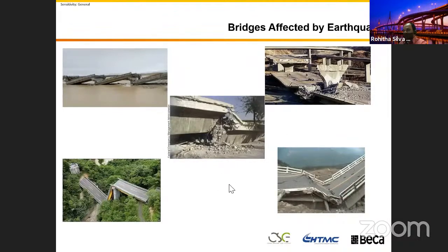Even a good thing in our Transport New South Wales, I think our RMS in here, when there's issues like that, they take that one on board. I remember when the Christchurch earthquake happened, immediately when we were doing a project, there was nothing in the code, but they came and asked us to implement certain details in the piling, the pile stirrups. We need to hook that one to make sure that it won't burst. I think they just pay some attention in here and refer to those codes, try to implement them.